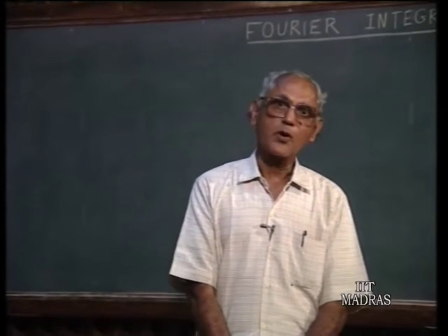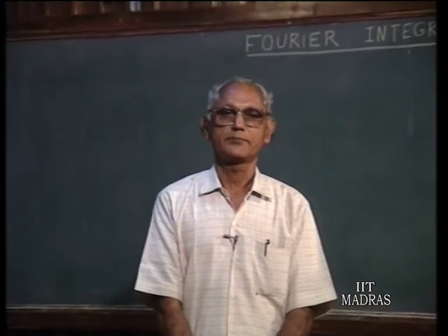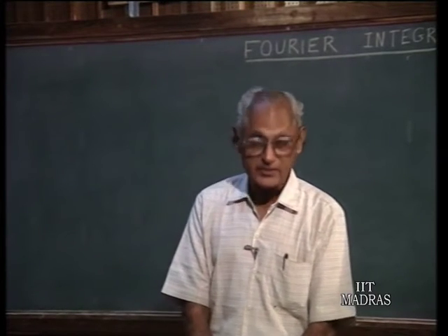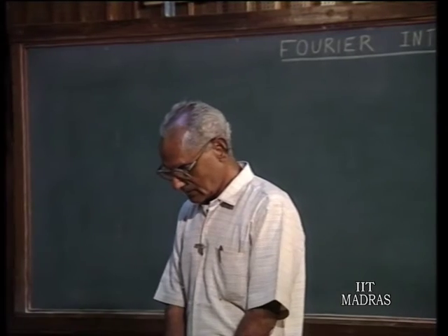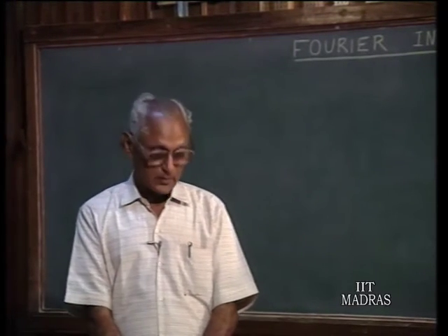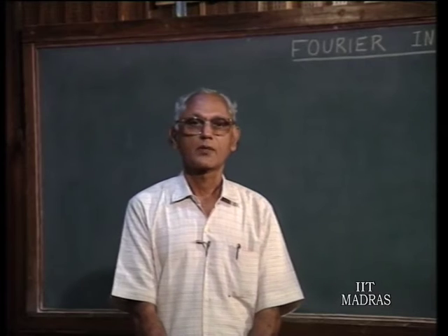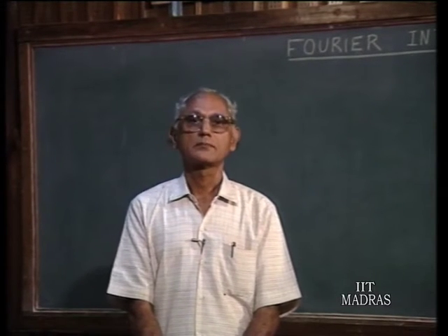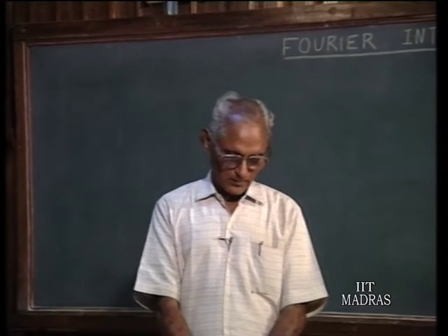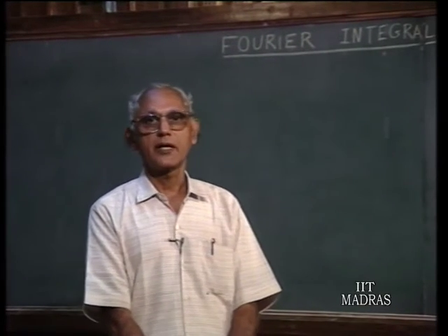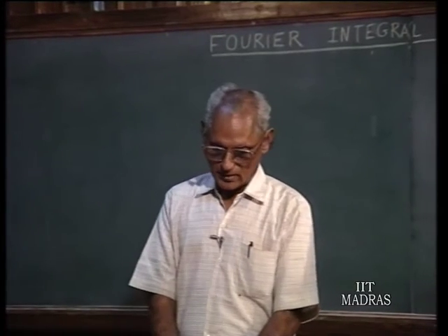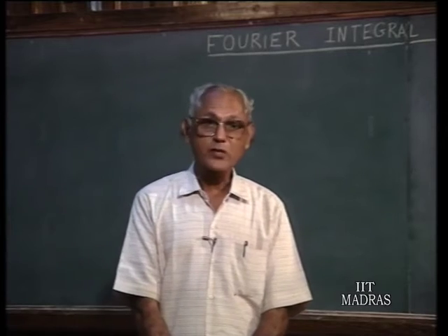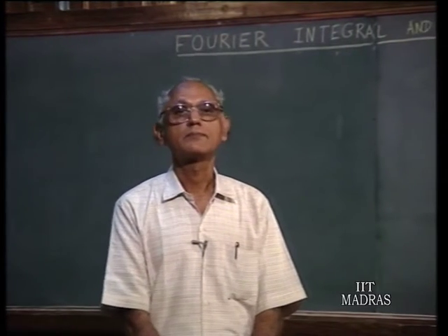This particular property is valid only for sinusoid. No other periodic function will provide such a characteristic. And once this particular property is satisfied, we brought in additional concepts like frequency response function, impedance and admittance concepts, which will simplify the analysis of linear systems driven with sinusoidal excitation functions. Now, this naturally led us to inquire